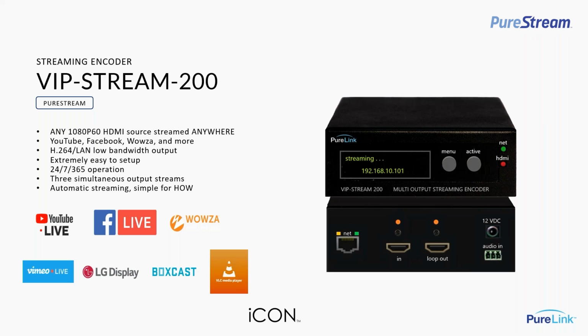Now it does 3 simultaneous output streams. So you can do RTMP or RTMPS as one of the streams, and then you could do RTSP or TS as 2 other stream types. So it does allow you to go to multiple platforms simultaneously. And once you set up the Stream 200, it's really a one-time setup using its built-in web interface that's extremely friendly. Then it's really just a matter of activating the output.